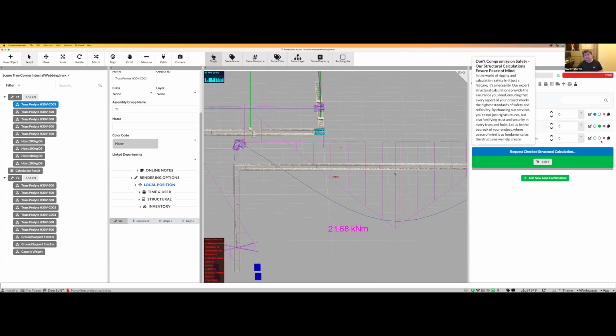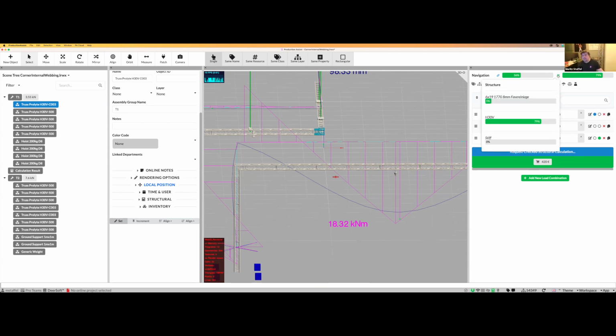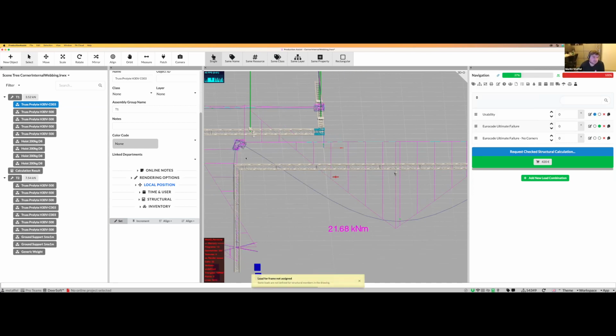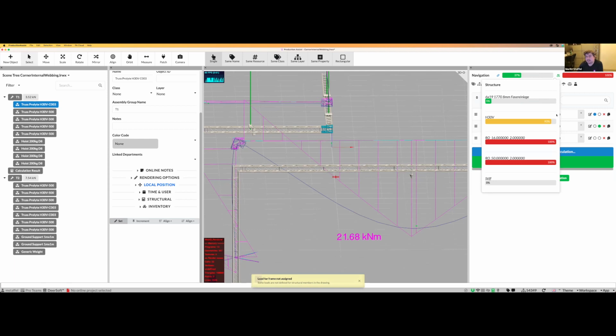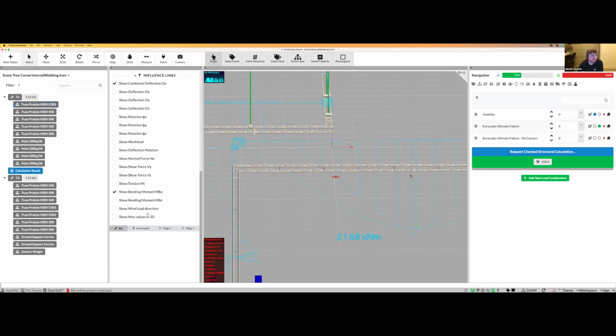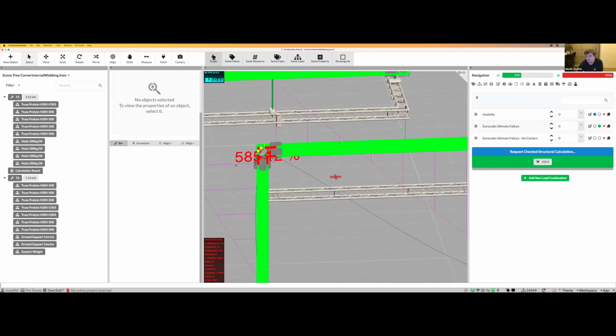But that's not all. If you calculate this just with the normal truss cross section and don't care about the corner, you would think that the truss is at 79% workload. That seems reasonable and would be a good thing to build. If you do the exact same thing with the actual trusses in here, you see immediately it jumps to over 100%. And if I now tone up the workload, you see you're at 600% workload.